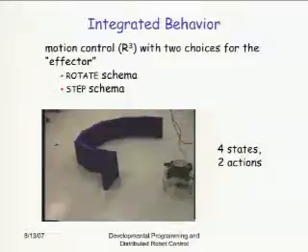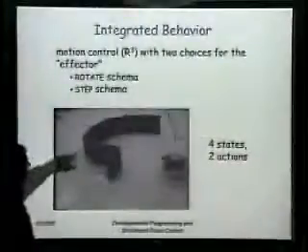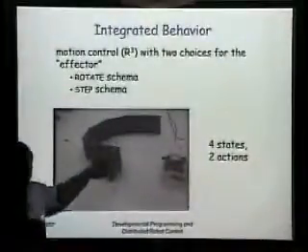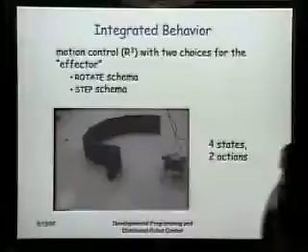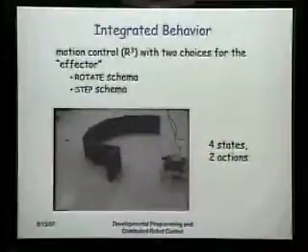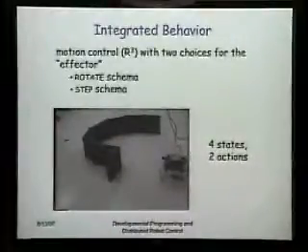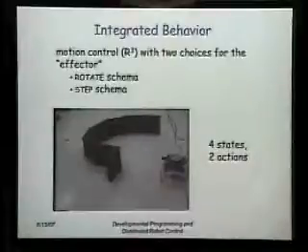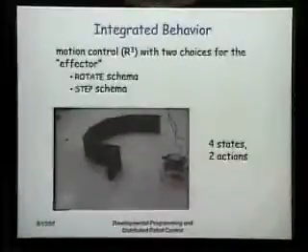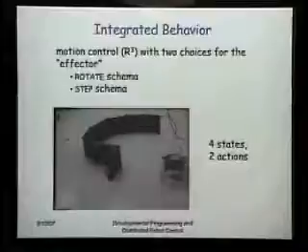Go to a third level. Now we know how to rotate and we know how to translate with the step macro. And we say solve this maze. This is a simple maze, but what it was supposed to do is get from this location here over to this little red X on the floor. It doesn't know about these obstacles in the way. It has to find a path. We said, don't use any primitives. Just for the sake of argument, try just rotate and step, those 2 macros we put together. It's got 4 states and 4 actions.